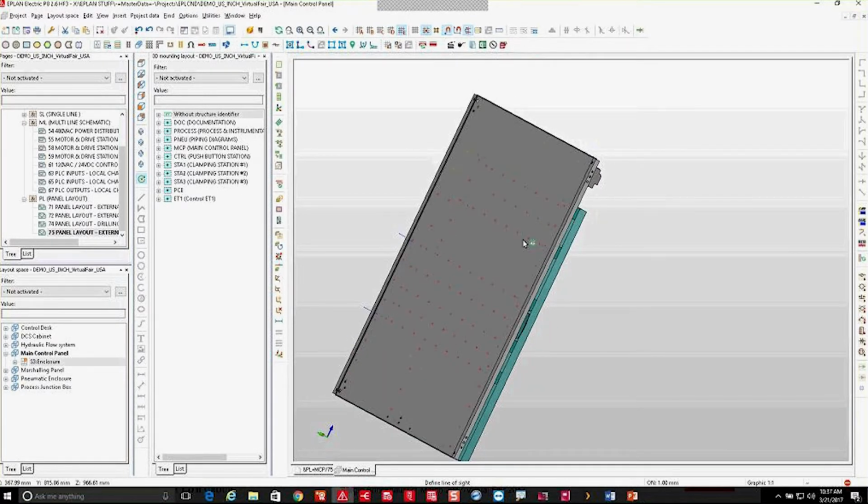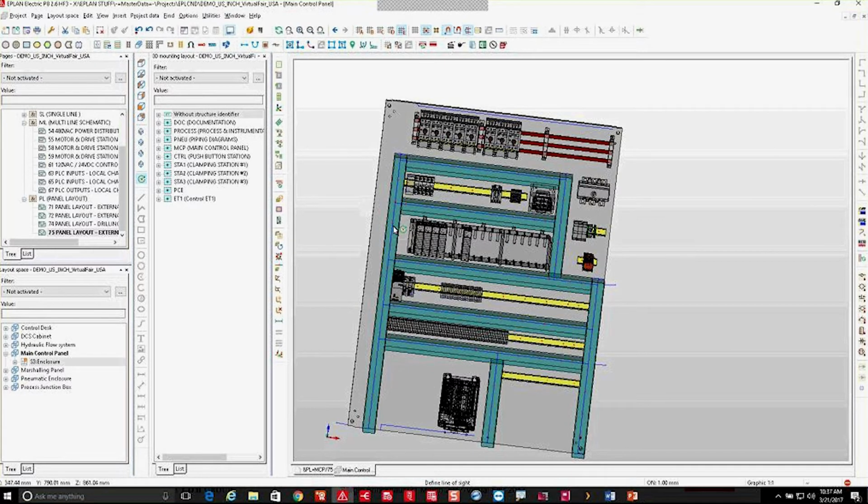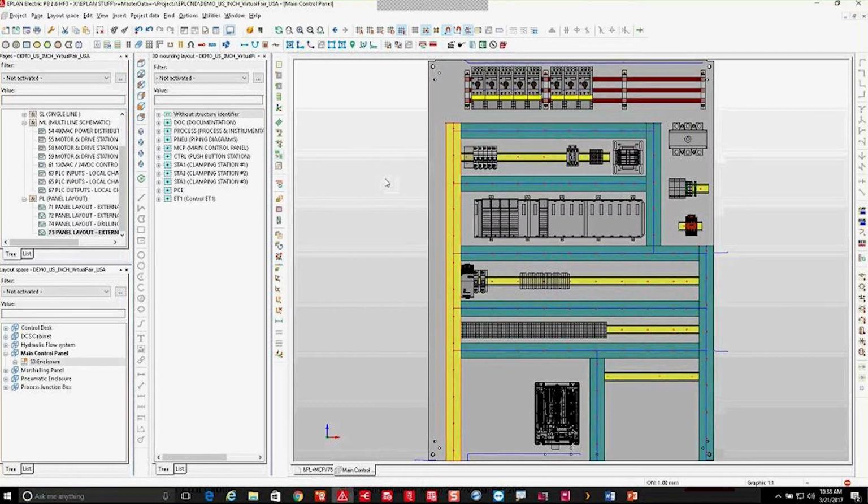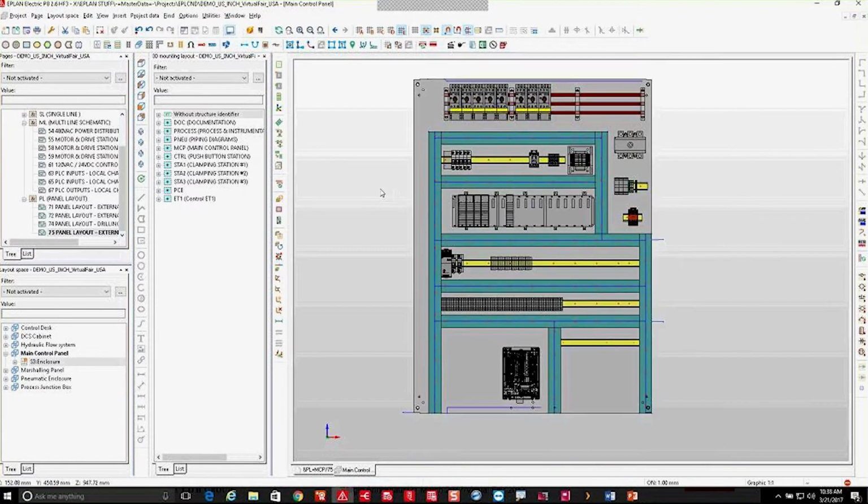So the benefit of this, again, is very easy functionality. As you're dropping your components, you're getting a lot of detailed information working for you in the background. There's also fill capacity for these wire ducts, and channel filters for the wire ducts as well, to let the system know I would like certain wires to go through certain channels and so on. A huge gain as you're using a tool and laying these components down.